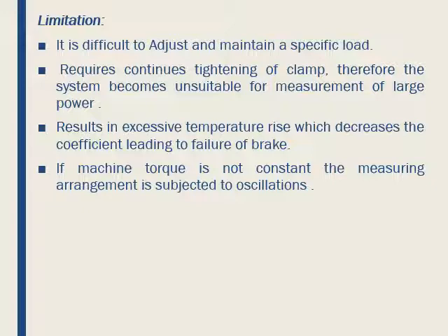So let us go to the limitations. The Prony brake is inherently unstable. Its capacity is limited by the following factors. The first one is the wear of the wooden blocks. The coefficient of friction varies between the blocks and the flywheel. Further, it requires continuous tightening of the clamps. Therefore, the system becomes unsuitable for the measurement of large powers.